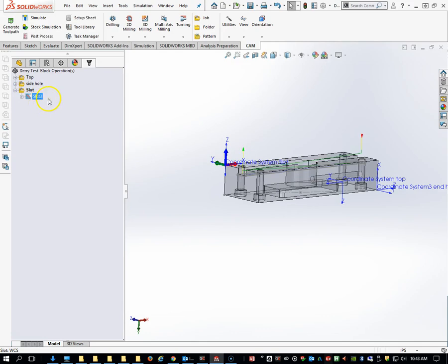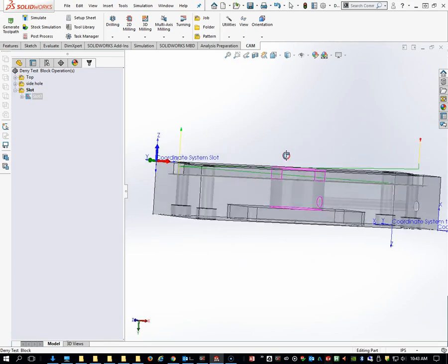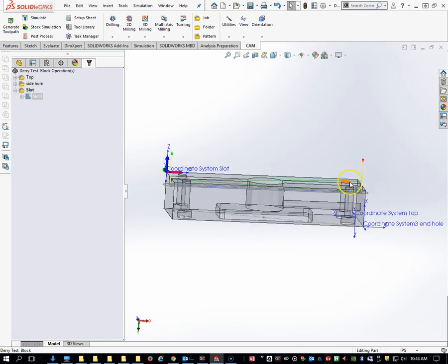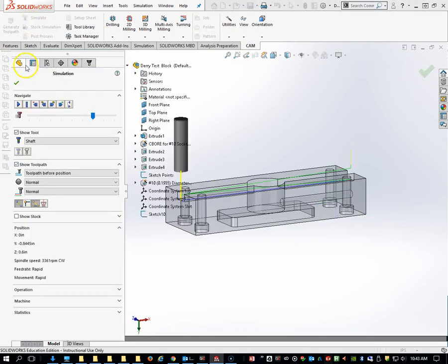It's going to generate the tool path, and notice how the slotting command works. Instead of spiraling in, it ramps down, and then does a final pass on the level. So we can preview that with the simulate. I'm going to slow it down a little bit.